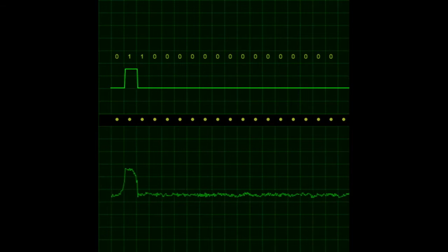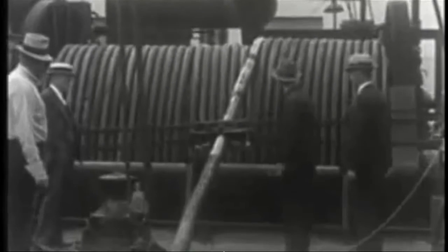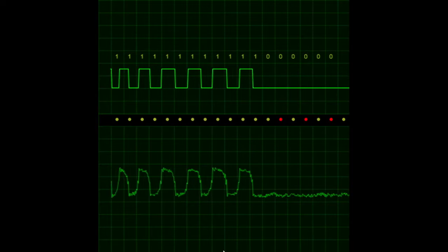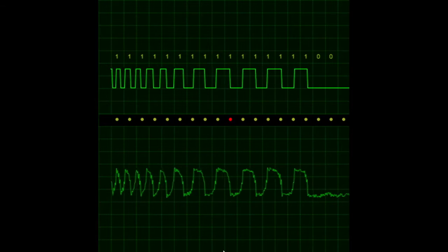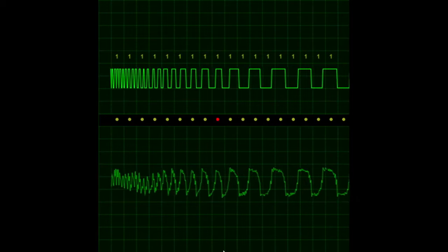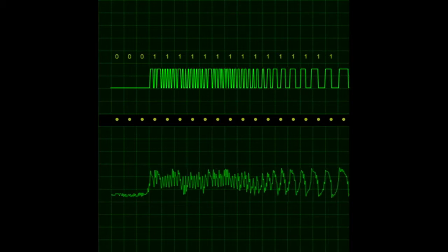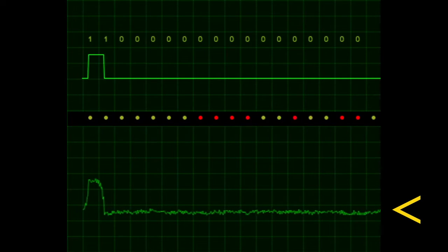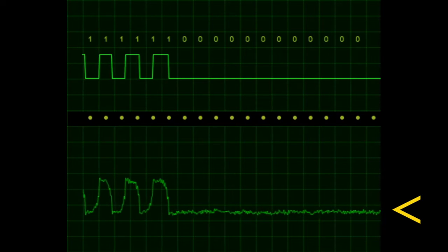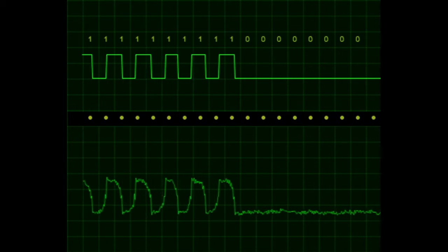Well, the limiting speed was not the clock. Then and today, the speed of transmission was physically limited by the minimum spaces between these impulses, or the pulse rate. And this problem plagued engineers who were testing underground submarine cables using the existing Morse code system. It's similar to an echo or a sustained note. If one sends dots too fast over a long undersea circuit, they will run together at the receiving end, because the symbol we receive at the far end of the circuit will be a slightly longer, smoothed out rise and fall, not an exact replica.